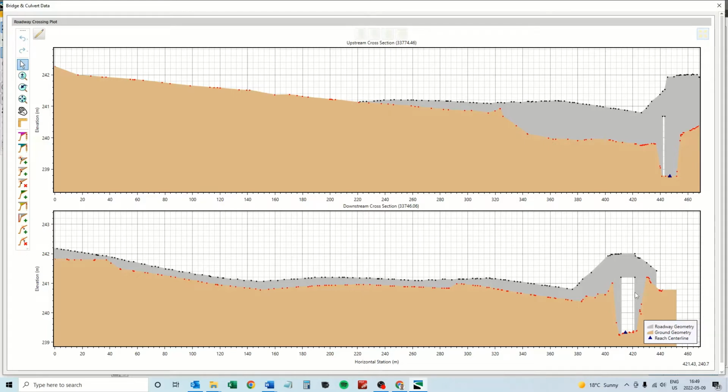Also, we were advised by the local road authority that there are 2 additional culverts across this crossing. They're I believe 1900 CSP culverts that act as relief during flood conditions. So we're going to add those in as well.